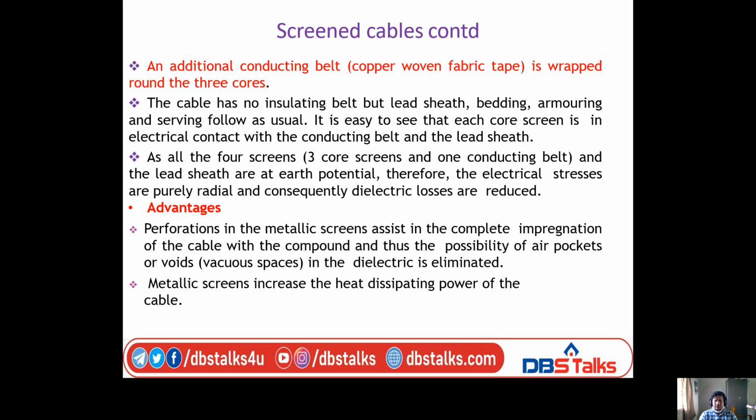What are the advantages of screened cables? Perforations in the metallic screens assist in the complete impregnation of the cable with the compound, and thus the possibility of air pockets or voids, that means vacuous spaces, in the dielectric is eliminated because of metallic screens.